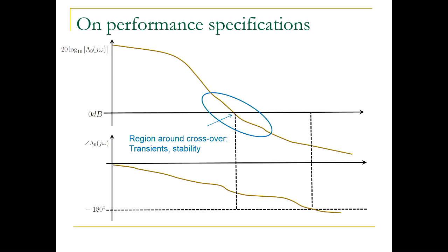So suppose that you do not have any poles in the open loop transfer function that are in the right half plane. What is the Nyquist criterion for stability in that case? That's the special case. So the open loop transfer function is stable, no unstable or on an imaginary axis open loop poles.